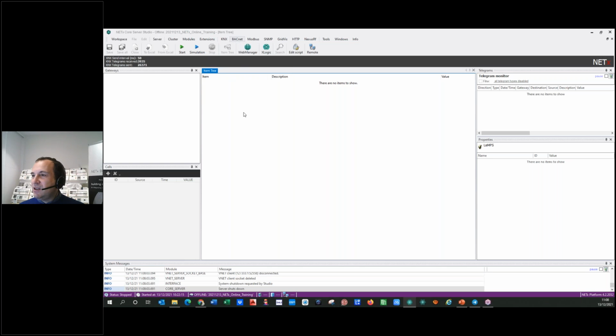So starting the Explorer, we get a message. This message is on the other screen. It says that my local host IP 127.0.0.1 is not valid. Okay, no problem. This is because we haven't defined the device that is going to explore the BACnet, which is the IP address of this network card.